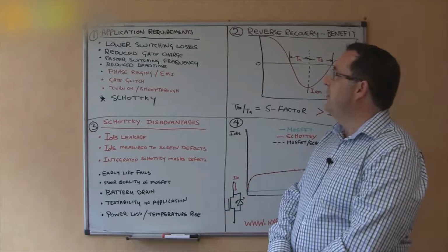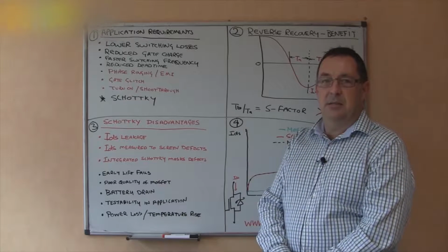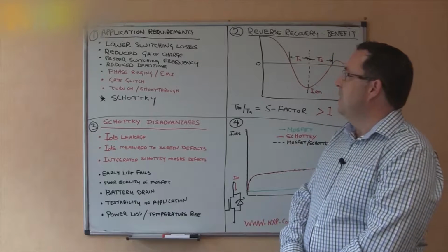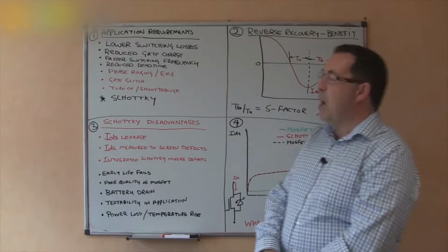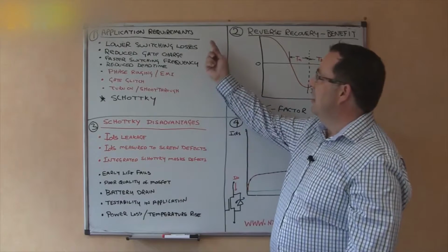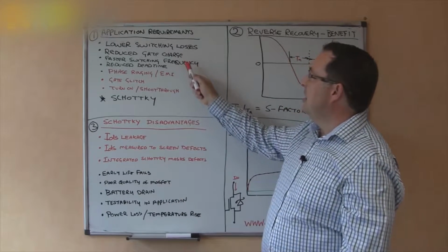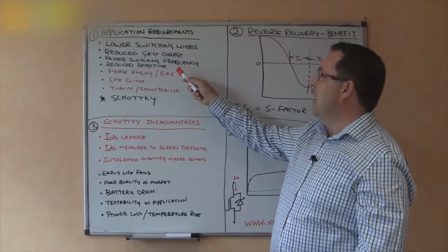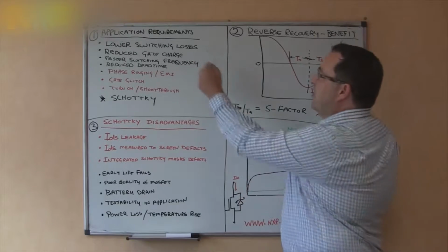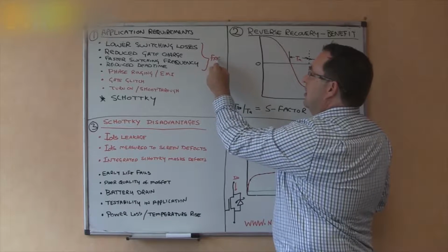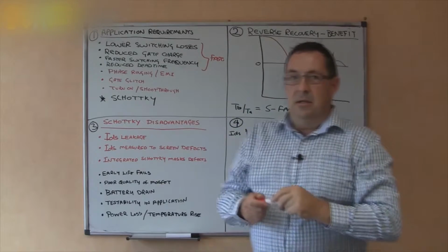As demand for higher efficient power supplies has been going up over recent years, this has resulted in a requirement from the market for lower switching losses, reduced gate charge, faster switching frequency and reduced dead time. And because of all these, we've resulted in very fast switching MOSFETs.